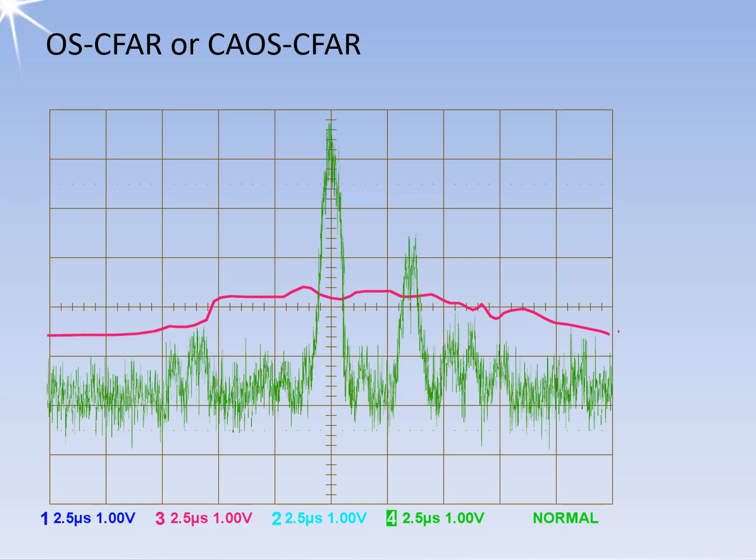The advantage of OS-CFAR is the significantly improved effectiveness of threshold value creation. Neighboring target signs can no longer mask each other. However, a significant disadvantage is the immense computational effort that has to be provided during real-time processing of the radar signals, since the threshold calculation comes before the target detection.